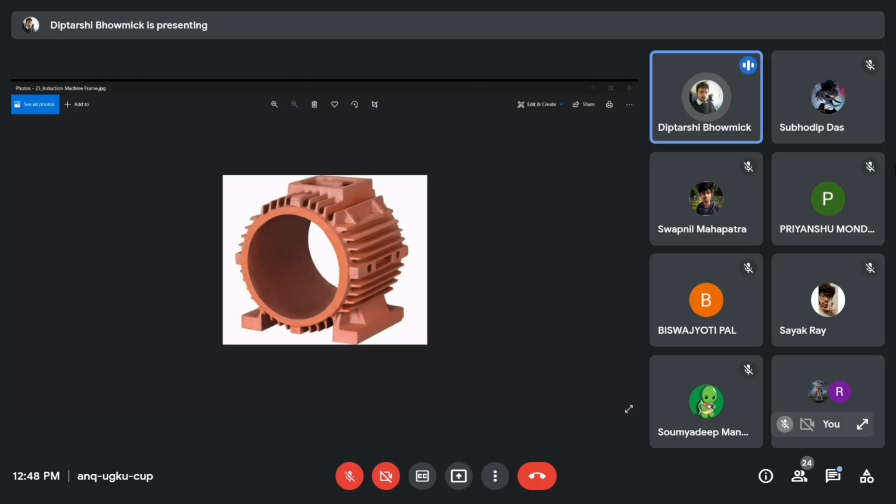Now the length and thickness of the stator housing. The length you have to measure. So this is the length, and this is the thickness. Clear? Length is 21.5 centimeter and thickness is 1.75 centimeter. The function of the stator housing is the same: to support the poles, to increase the internal stability, and to provide a return path for the flux. That is the purpose of the stator housing or the frame.